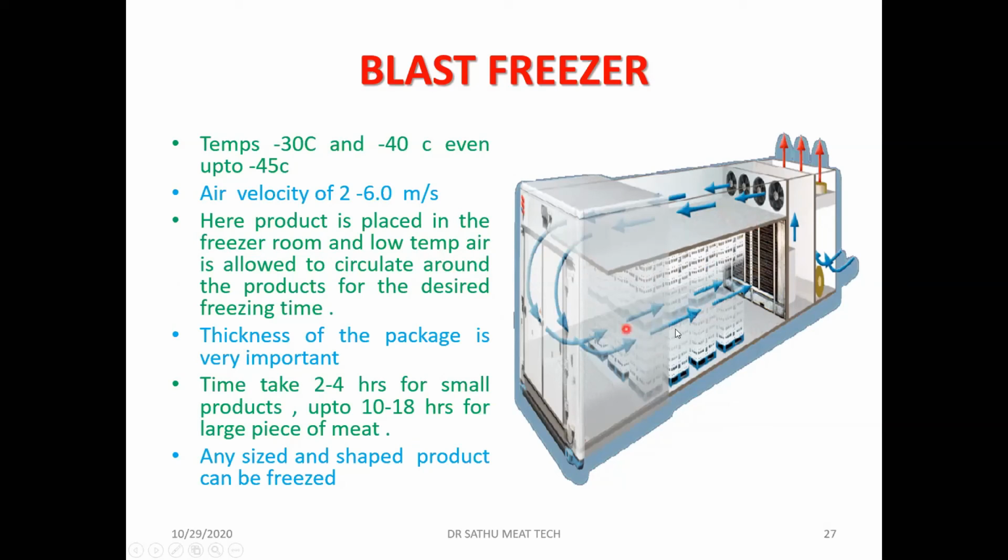Once it is frozen in the blast freezer, it is taken and kept in the frozen storage, which is normally maintained at less than minus 18 degrees centigrade. It is not advisable to store here itself because the cost of storage will be more. If you go to a lower temperature, the cost of storage will increase. So once you freeze it, take it out and keep it in the frozen storage.